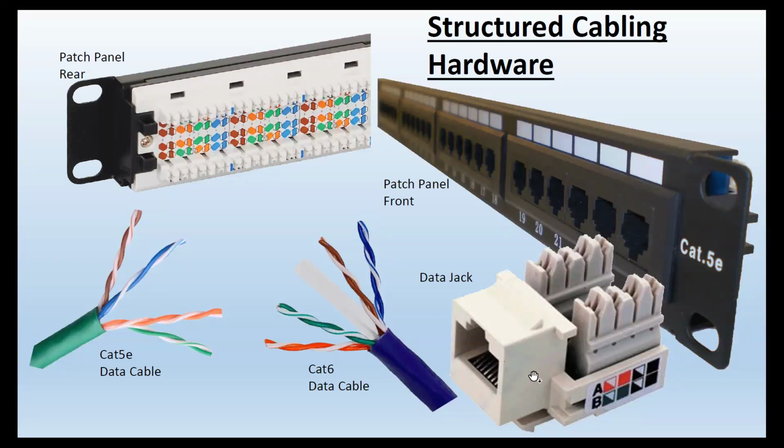Configuration. We were going to talk about what T568 is, but this is the color code. This jack has this type of a sticker, and let's say A or B configuration. So if it's A configuration, these two would be the orange pair, and these two would be the brown pair, for example. This one here would be orange stripe, and this connection here would be orange solid, and over here brown stripe and brown solid. And on the other side, who knows, because this we can see the sticker.